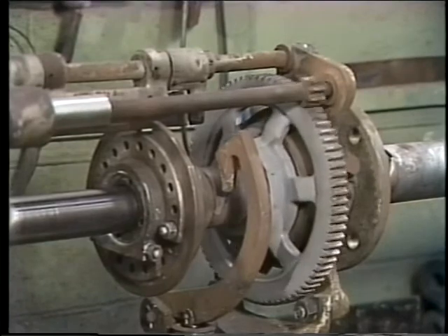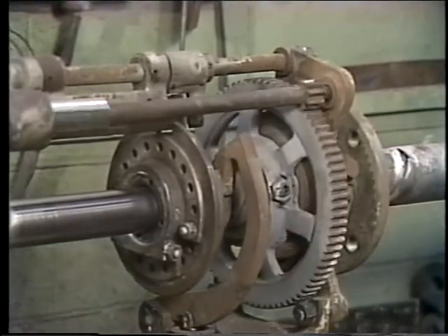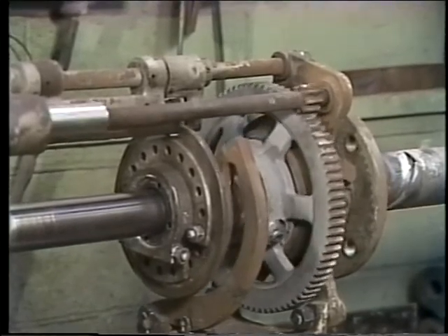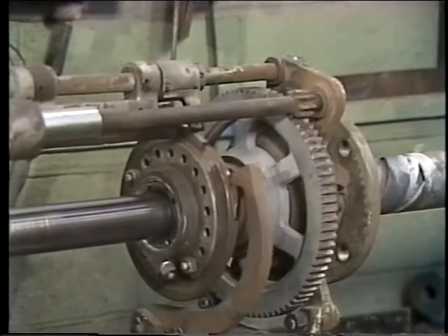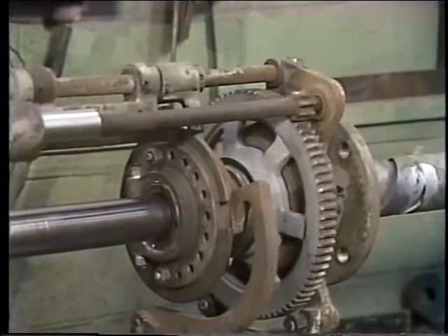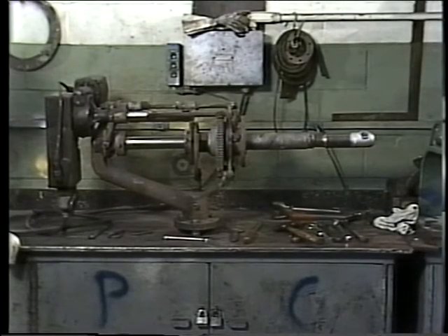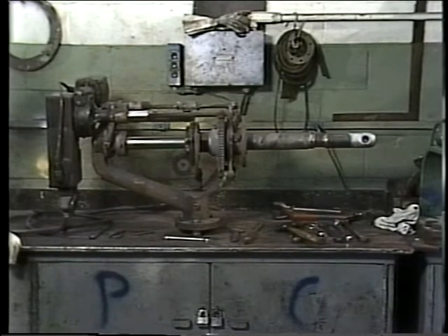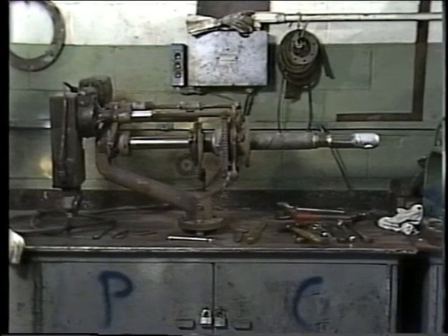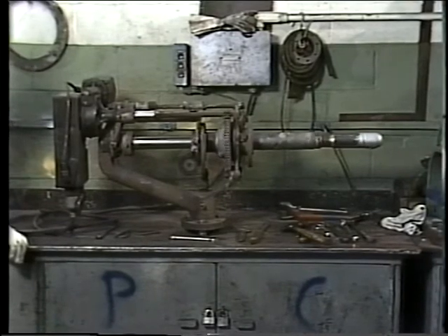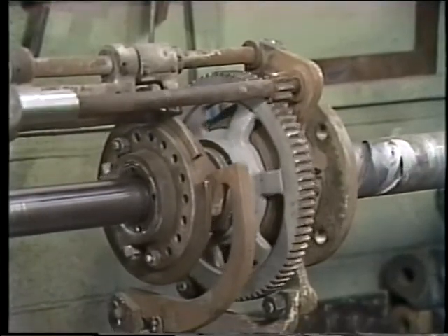On short tube retractable soot blowers and rotating stationary blowers, the timing of the blowing cycle is determined by the cam on the element. If the cam on one of these is mounted wrong, or if it is cut for the wrong blowing arc, then you'll have to determine where the problem is and try to cure it. Usually, you won't be cutting a cam to change the blowing arc while a soot blower is in place. Ordinarily, that's done most often while the component is in for shop maintenance. But it is possible to find that one was put together wrong, or that the blowing cycle for that particular blower is wrong for its location.